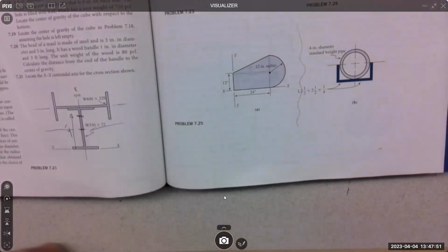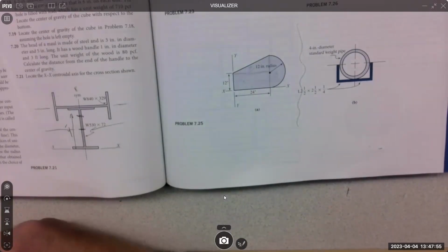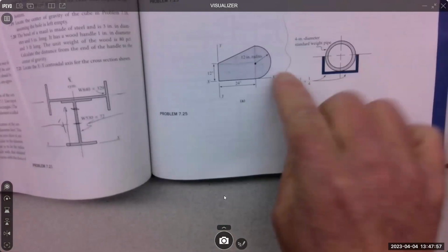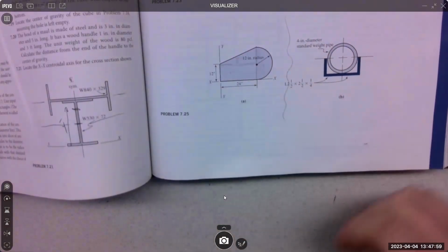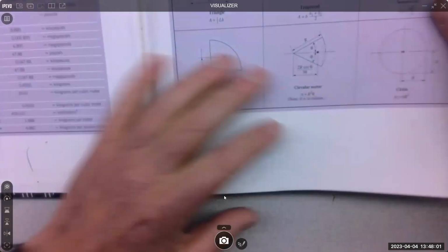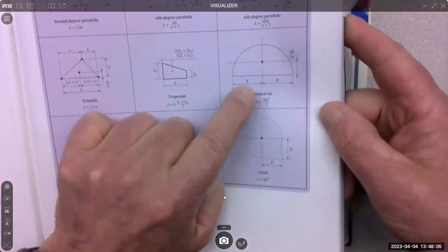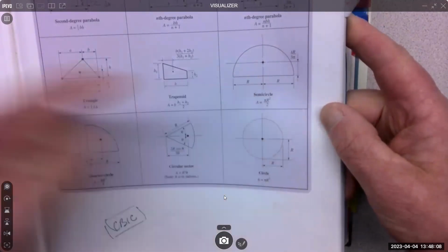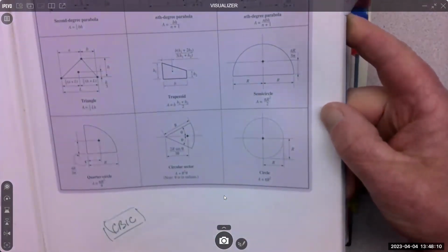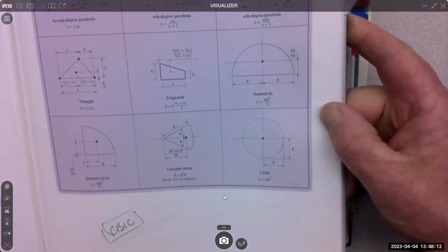You're just going to have to come up with some creative shapes. So if you do a half circle, right? Maybe half circle, triangle, rectangle. That's how I have it broken up. Half circle is here, front cover of the book. We would have to do the whole circle and then after we get the centroid, we can cut that.